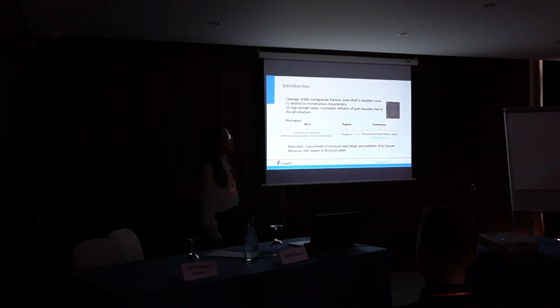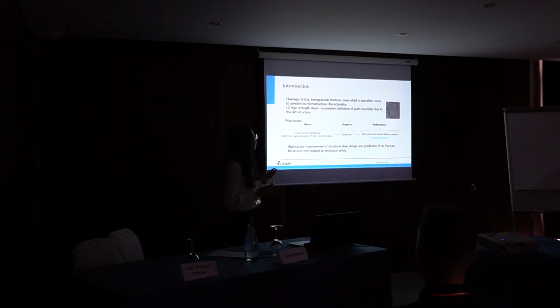crack. There are several challenges in the modeling of cleavage, and the most important one is that cleavage is very sensitive to the microstructure characteristics. Even though there are some simple ways to relate the fracture toughness or the fracture stress to, for example, the grain size through the Hall-Petch relationship, or the RKR model to estimate the cleavage stress at a certain distance before the crack tip.